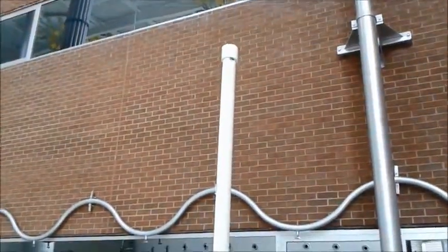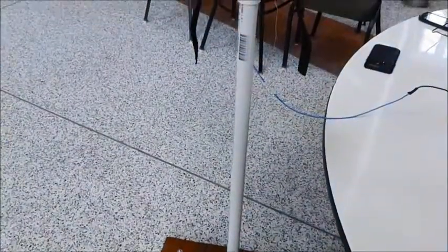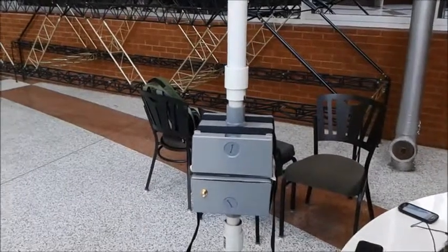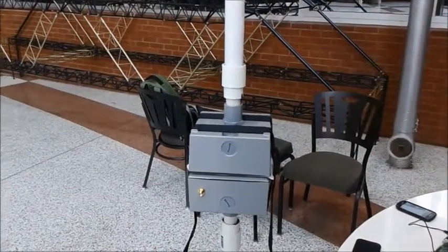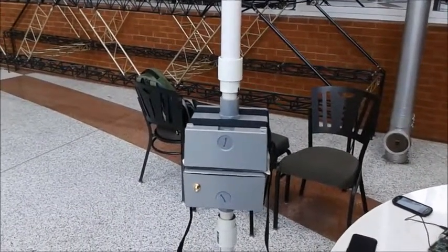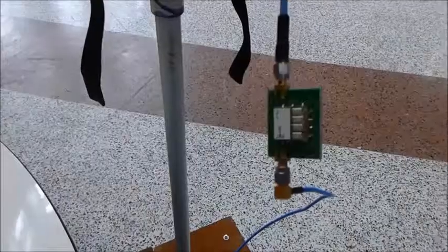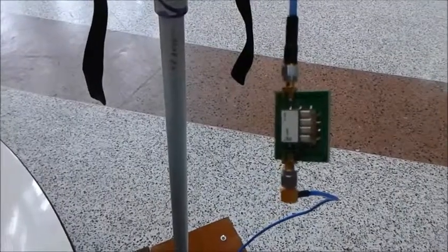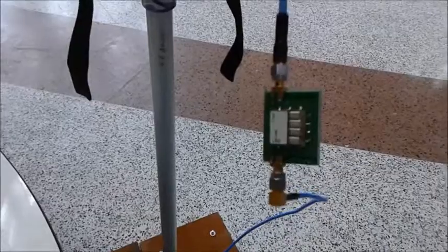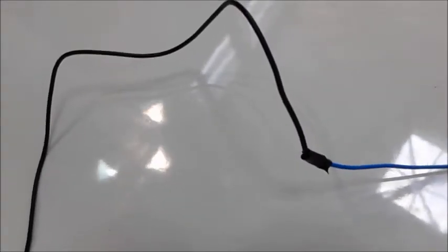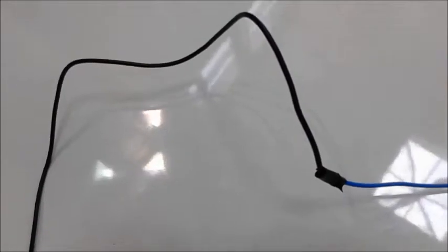The upper section of the antenna is for 1090 megahertz. The lower section of the antenna is for 978 megahertz. Since the SDR only receives one channel at a time, unlike our design, we're only using one half of the antenna at a moment. We're still able to use our RF filter from Mini-Circuits, and we've spliced this into the MCX type antenna connector for the dongle.